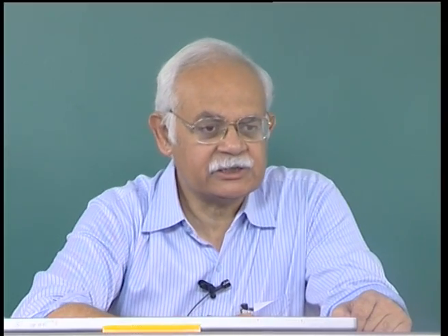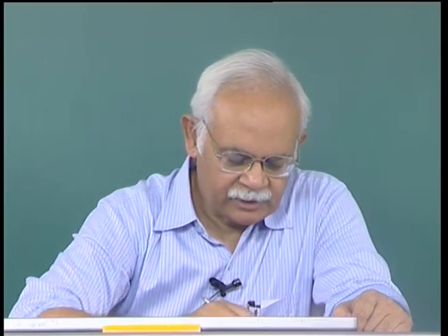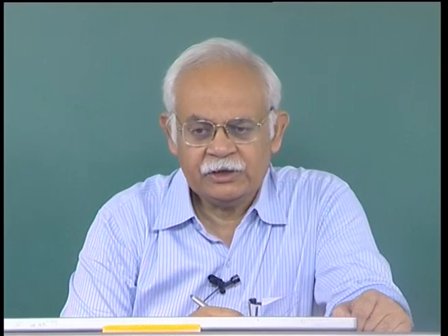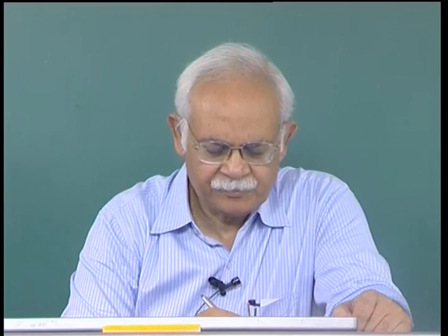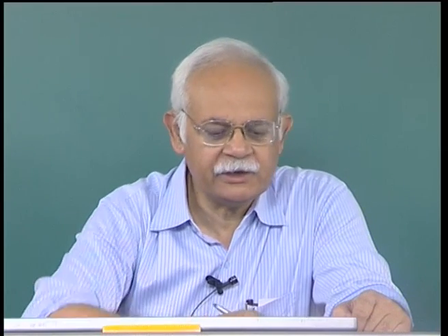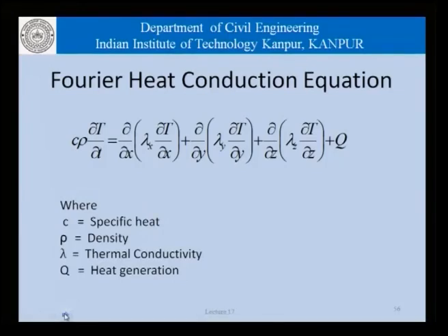Now, having seen the experimental results, let us try to see what goes on in a numerical simulation or an analytical study of mass concrete. What we really need to solve is the Fourier heat conduction equation, which gives us how the temperature varies with time in a three-dimensional space when there is a certain amount of heat generation taking place in that block of concrete.